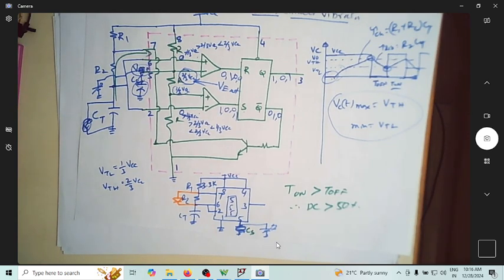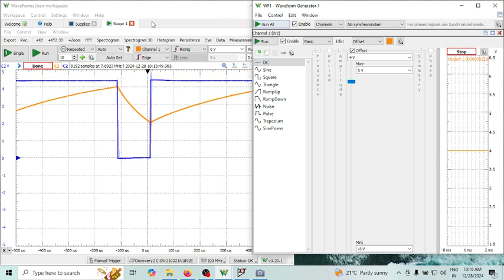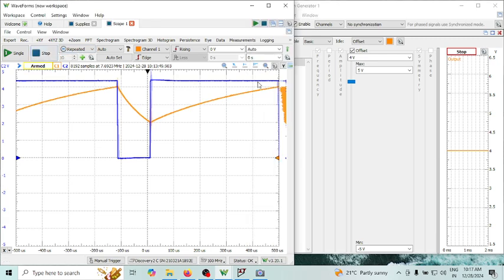So now connecting. Okay, now I have connected a diode in this configuration. Now let me run and try to see. Let me take out this control voltage for the time being. I will make the control voltage 2/3 VCC only, so I'm not using this. Let me just run this now.